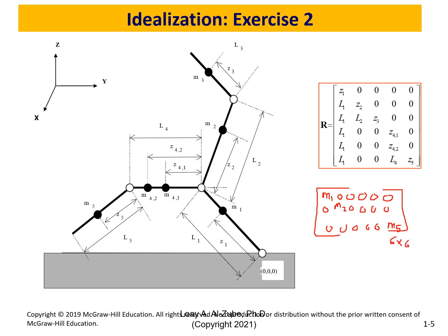You multiply, do you know what's a transpose? Rows will become columns and columns become rows. So you take R matrix, do the transpose of R, multiply by this diagonal matrix, then by another R. This is called the generalized mass matrix. So in biomechanics, instead of using one mass unit of one value for one mass, I'm going to use this to do the analysis. Because I have now a lot of segments connected to each other. And that's called the generalized mass matrix.